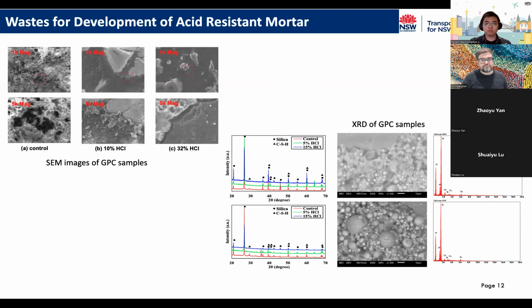We did SEM, and that showed a notable formation of micro cracking, high surface roughness and porosity when we increased the level of acid exposure.